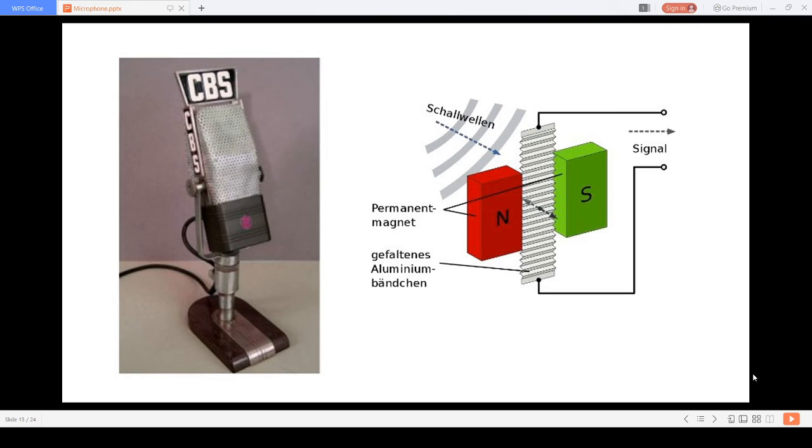The working of the ribbon microphone: in a moving coil, or dynamic microphone, high frequency response is poor because of the mass of the diaphragm. Mechanical mass is equivalent to electrical inductance, and this attenuates the high frequency. To increase the high frequency response for audio frequencies, a very light aluminum ribbon is used in place of the diaphragm. In the coil assembly, the ribbon acts as a conductor as well as the diaphragm. Such a microphone is called a ribbon microphone. Here is the circuit diagram of the ribbon microphone.